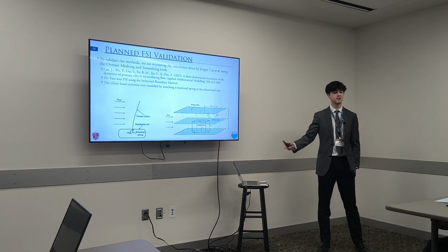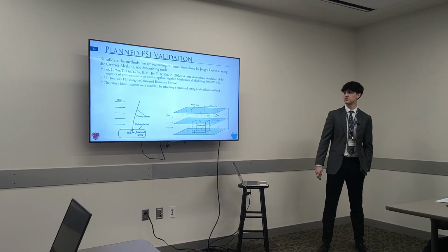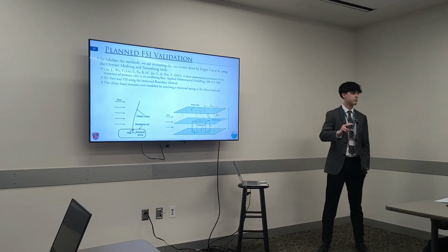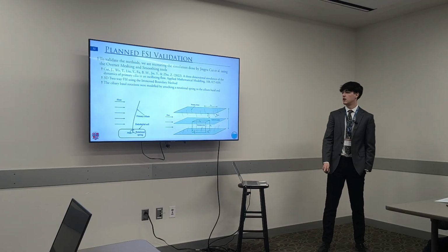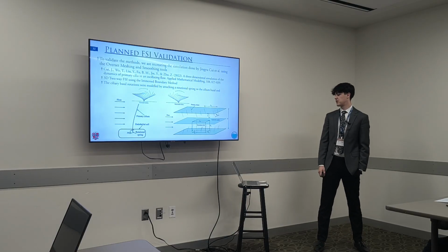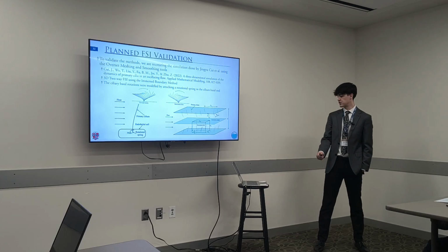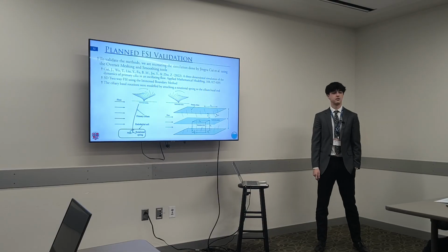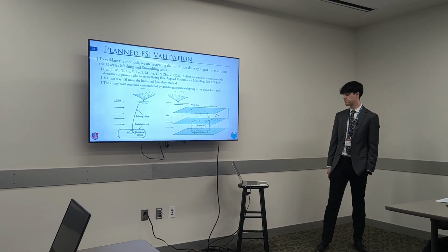Basically, the ciliary basal rotations were modeled using an attached rotational spring at the bottom of that cilia, as you can see there. But this immersed boundary method has difficulties in resolving thin boundary layers, and it overwrites the velocity values in each grid point to satisfy that boundary condition.